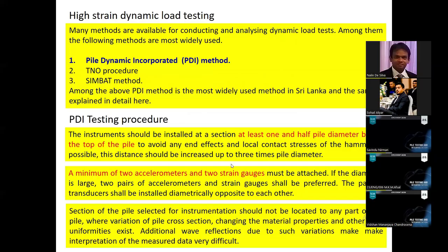The testing procedure, let me explain the testing procedure. There are different testing procedures. This Pile Dynamics Incorporated method, the PDI method, is the widely used technique in Sri Lanka. There are other methods as well. They are not popular in Sri Lanka. We don't have a lot of experience in the TNO procedure and the embedded method. The Pile Dynamics Incorporated method is the widely used analysis technique in Sri Lanka.